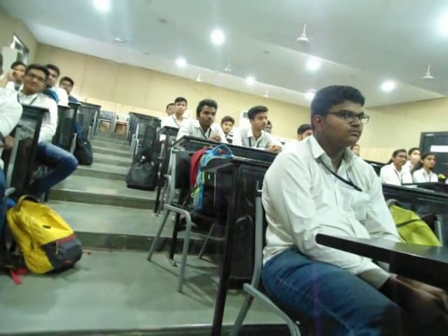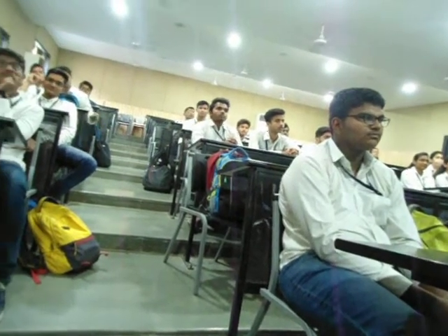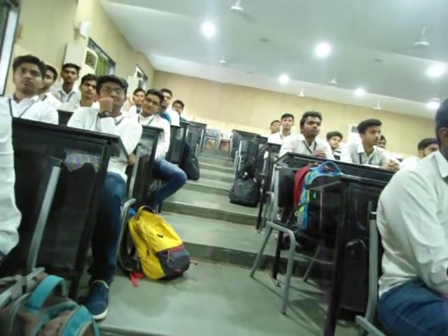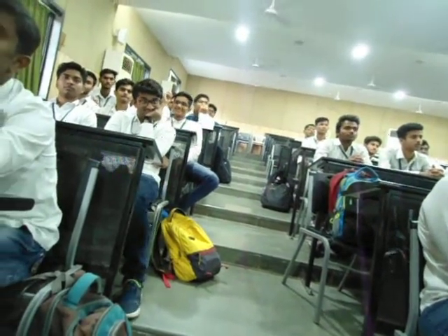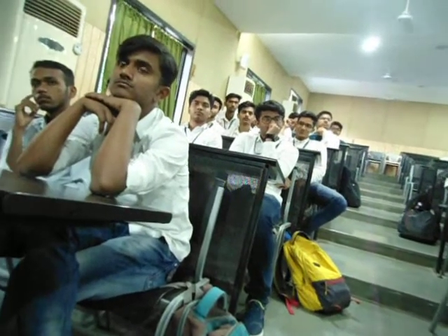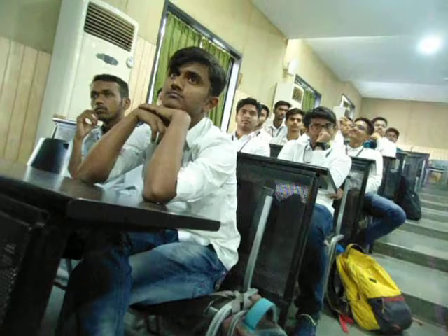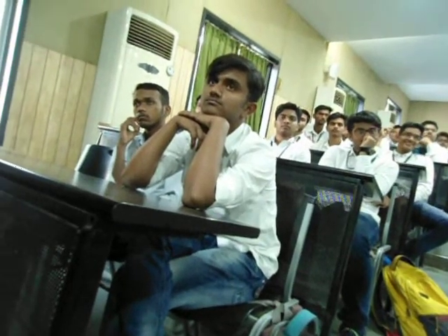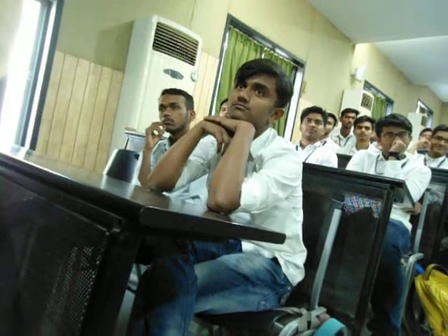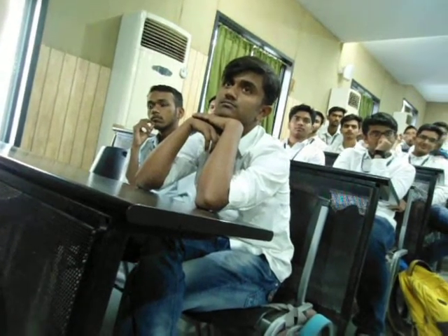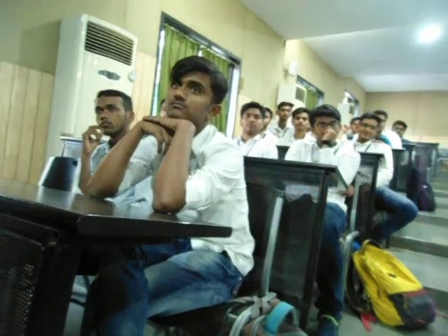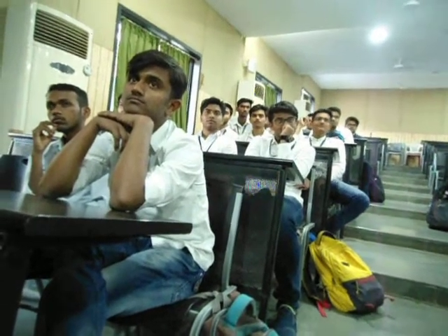Now construction of polygons. If some students have doubt how to construct a polygon, or about the different types of polygons. Hi, welcome. In this session, we will study various methods to construct different polygons. First, we will construct a regular heptagon with a side length of 25 mm. We will use the inscribed circle method to construct this heptagon.